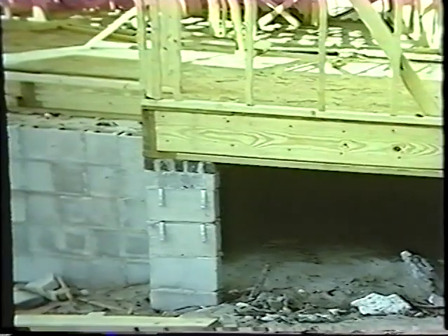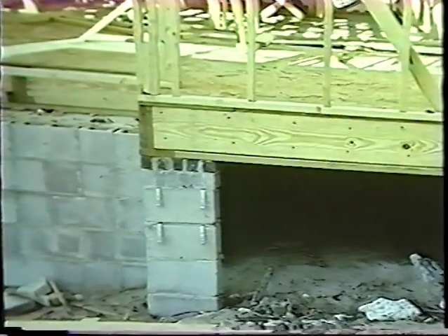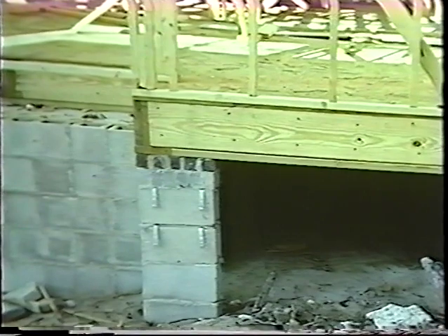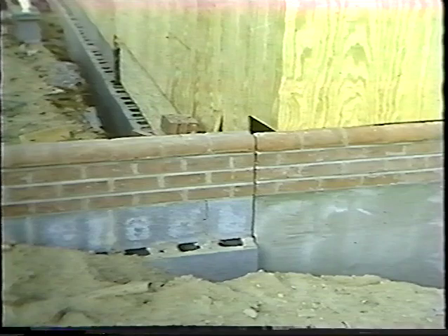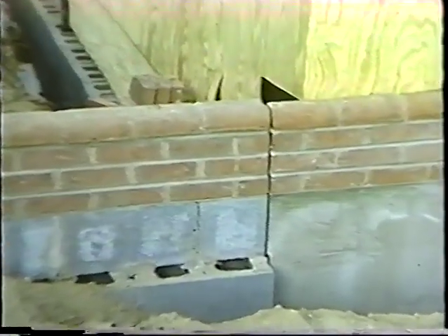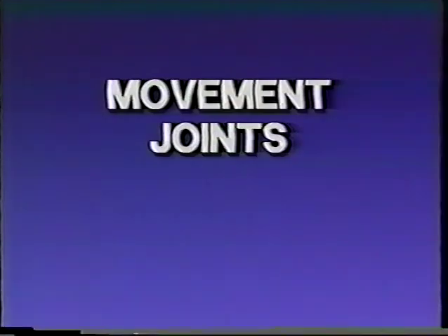Concrete masonry and wood shrink over time. The shrinkage is opposite to that of brick's growth. So, essentially, we add together first the positive growth of the brick with the negative shrinkage of the concrete masonry or wood. To avoid cracks, a series of movement joints should be installed in large masonry areas to allow the movements to occur. Two movement joints are used to accommodate these movements: expansion joints and control joints.